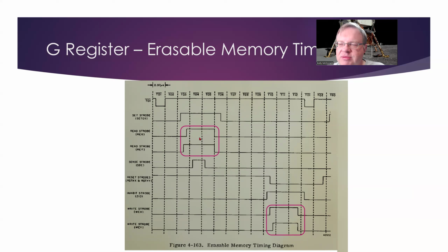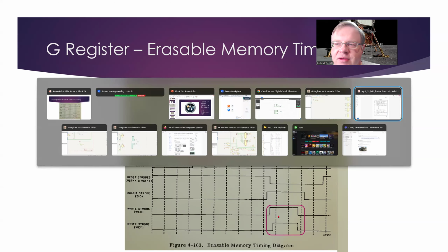Read gets a little bit more interesting because, with the timing, there is not only the potential to read data out of erasable memory and fixed memory, but we can also be reading the contents of the write bus or the L register, depending on what's happening. Where we start loading data in from memory is something we'll cover in the next episode, but we will be able to talk a little bit about the write in this episode. Okay, let's take a quick look at the design.